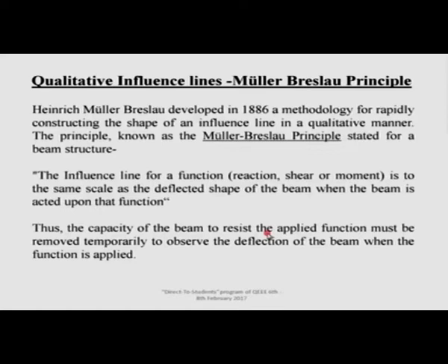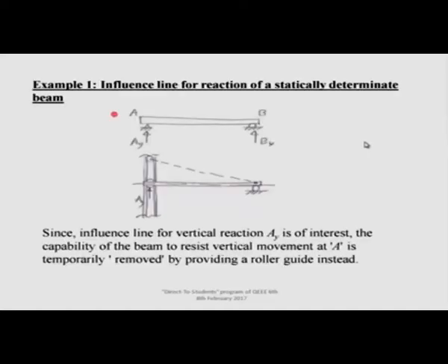What I am missing is that if I put a unit load, I will be able to accurately determine the reaction due to that unit load numerically, but that is not possible here. The shape will give a ratio of deflections and deformations at different parts of the beam, and I need to bear with that. So, I lost the quantitativeness, but I may gain better insight into the behavior of the structures for the influence line.